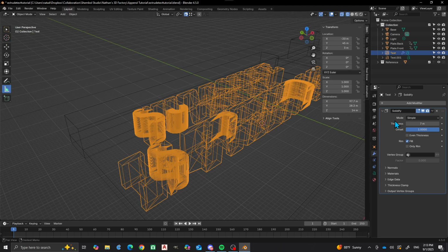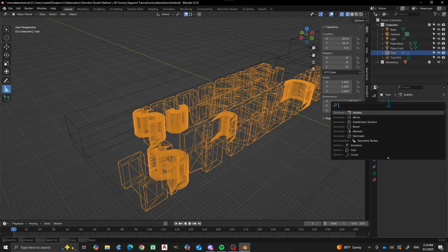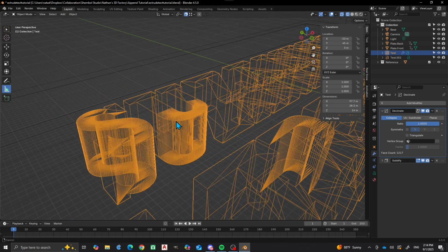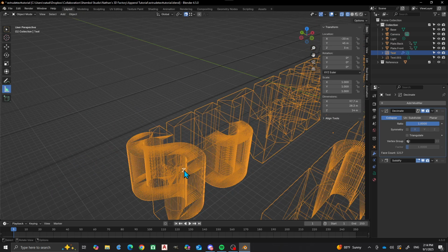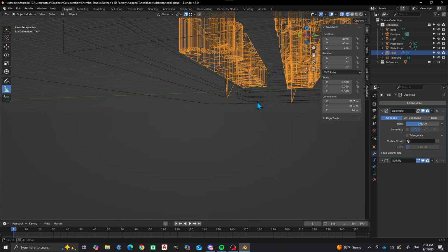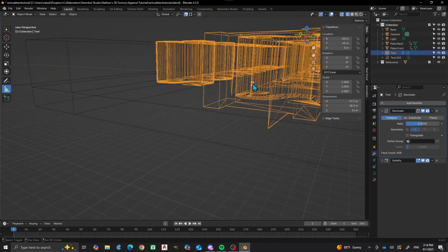the solidify modifier. So another thing I looked at as well is, can we do a decimate or a retopo? And this one we want to put at the top of the stack here. Let's see, and it was not decimate, because decimate will take it so that it just reduces the number of polys count. So we could say 0.5. Yeah, it looks pretty cool there. But again, you still get those unpredictable results.